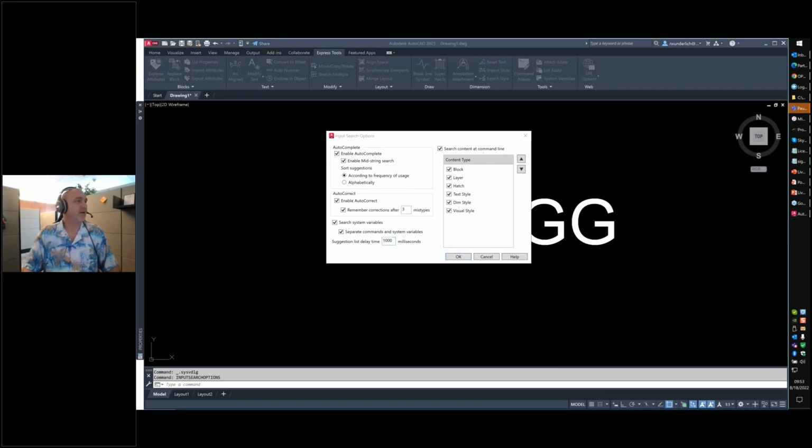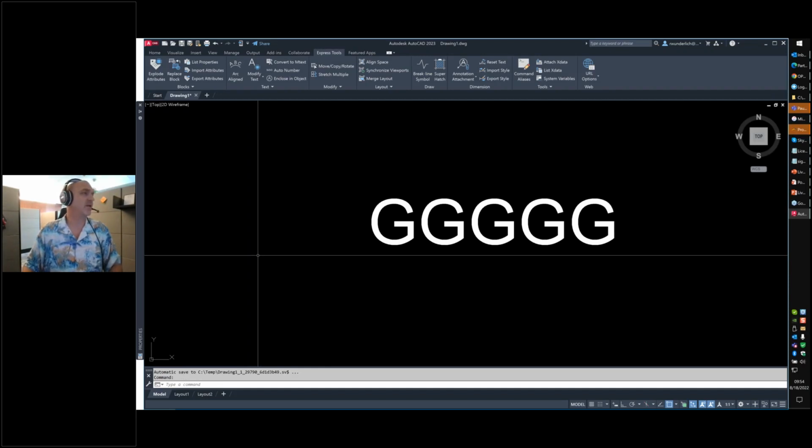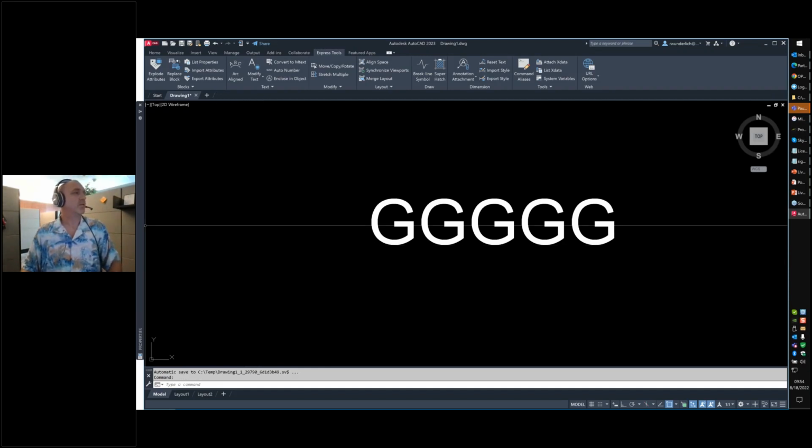So let's see, when converting DGN to DWG, I end up with unknown fonts called DGN1. I've not been able to find them on the web. Do you have them and where did you get them? Brian, you're going to end up with a lot of those from DGN. So what I generally do is that if you have those, go into your DD style, your text style, and then basically strip out whatever it's looking for and put in something that is on your system.